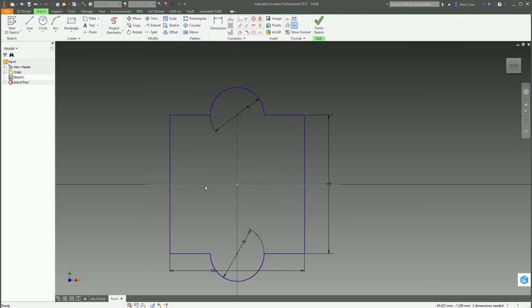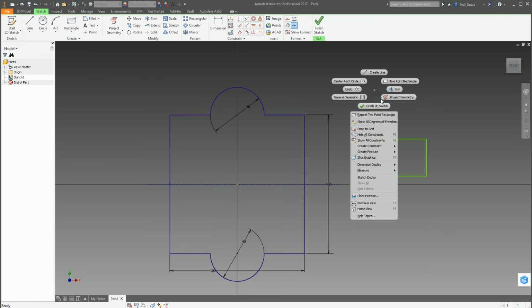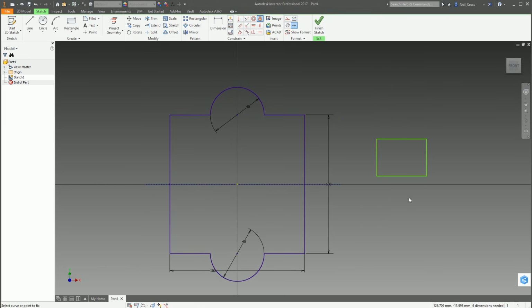It cannot move anywhere. And you can do that actually for any object really. So there's a square, right click, create a constraint, fix, and then select any of the lines here. And rather than having to do horizontals and verticals, if you're happy that the object is as it should be right now, it is in the right position right now, you can just fix it.